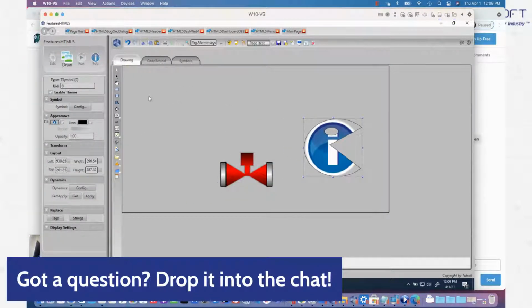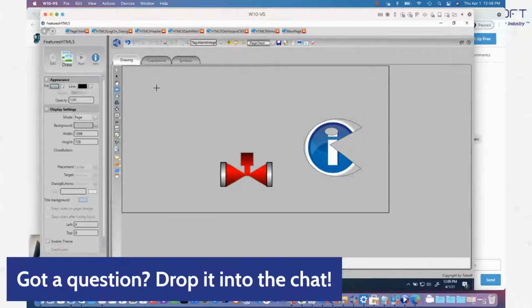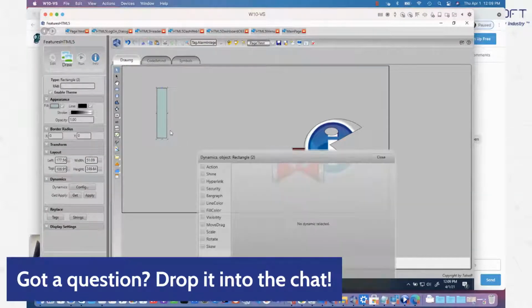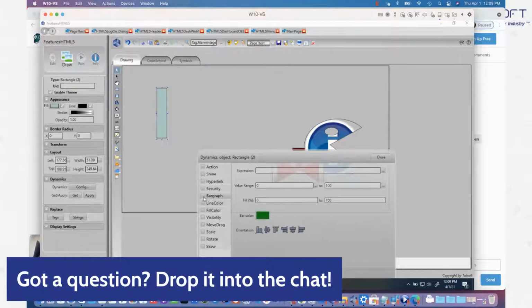And let's say you want to not use our library, because we have some PIG faceplates, but you create your own PIG faceplates. So here I'm going to put this bar graph mapping to the property pig.setPoints. I will duplicate that object, but I will remap it to pig.pv.